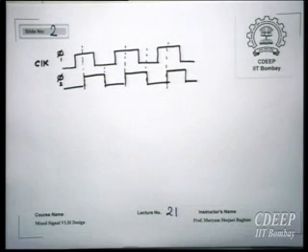But there are 2 problems with this. First of all, you want a PLL with a phase error of pi upon 2, and that phase error is too large. That means your loop gain is not too large, therefore that PLL won't be a very good PLL. You will have a lot of change in this error because your loop gain is small. The second thing is that you have 2 PLLs, and these 2 PLLs should be completely matched. So it's better to use one PLL and add different delay components to generate different phases. Of course, now the question is how these delay components will match. Then there are ways to improve this matching.